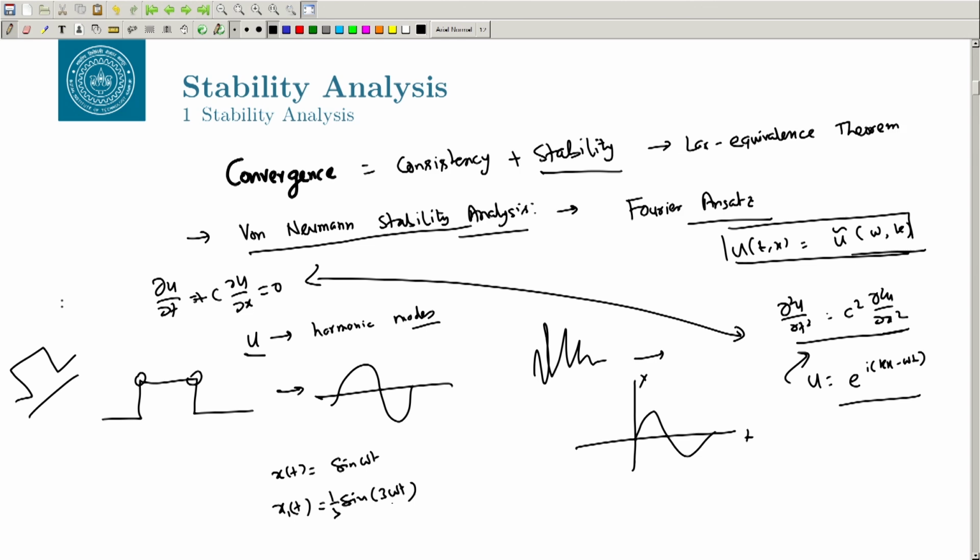So, you decrease the amplitude by 3 and increase the frequency by a factor of 3. If you plot this and then keep on adding terms, x(t) will be sine omega t plus 1/3 sine 3 omega t, plus all the odd multiples: 1/5 sine 5 omega t and plus 1/7 sine 7 omega t. If you do that, you will quickly start seeing the sine wave coming very close to your square wave.